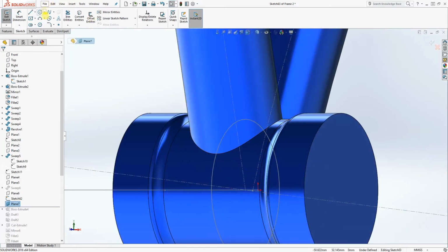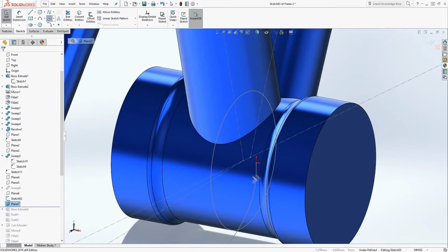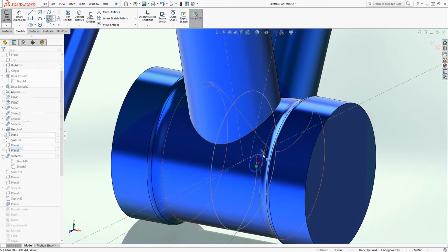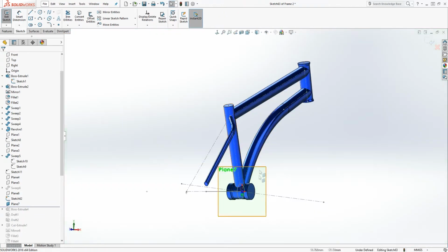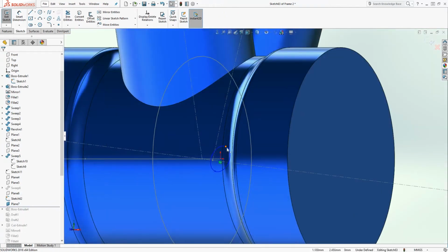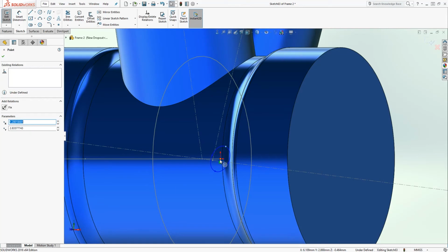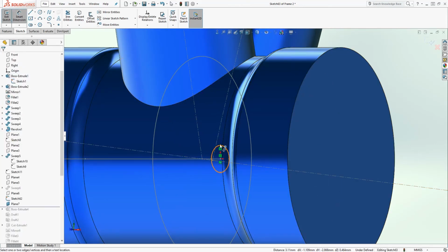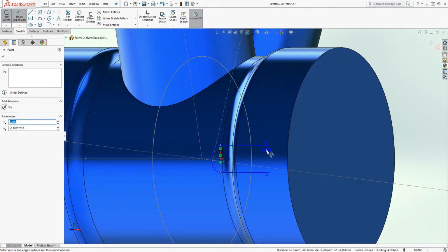The same thing we did with the other one, we're going to draw an ellipse. You probably have to bend it to see that origin point. Just draw an ellipse, something like that, and go normal to now. Click that point and the origin point and make them vertical to each other. I think we made this 15.5.